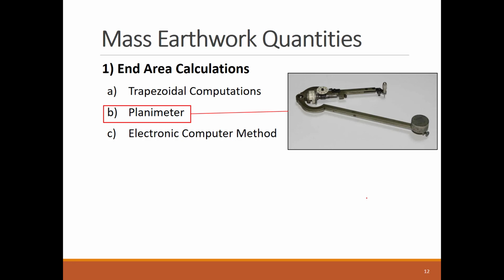The second and third methods represent an old and a newer way to calculate the road excavation cross-section area. The second method utilizes a planimeter, which is a tool that you fix on one of its ends and use the other end to trace the shape you want to calculate its area. Planimeters are old tools for estimators from when computer tools were not invented yet.